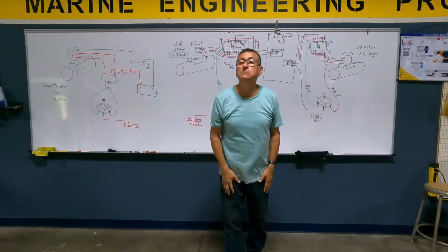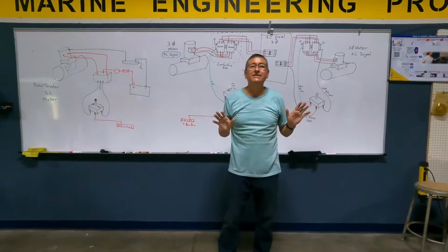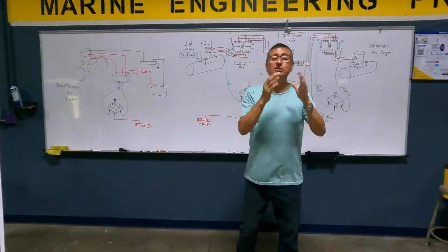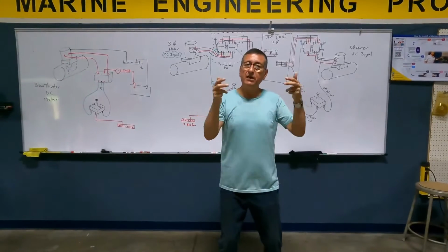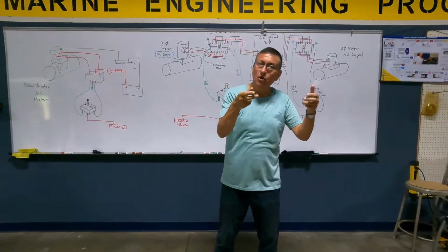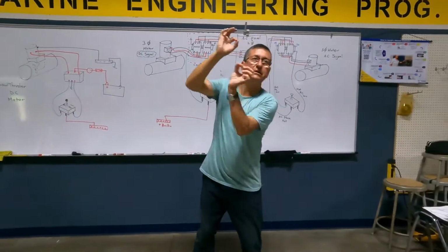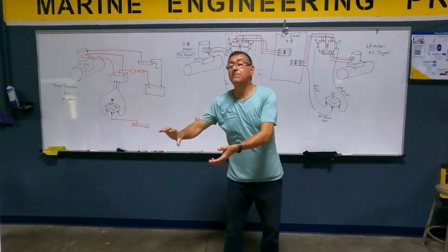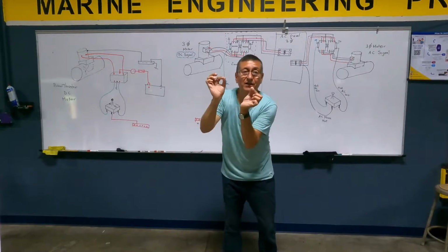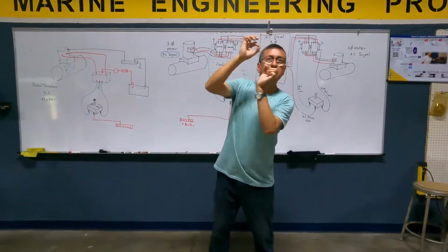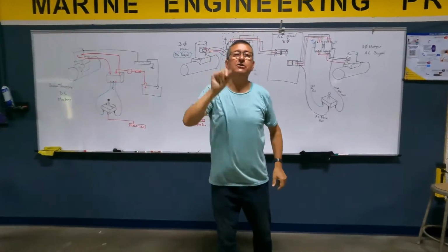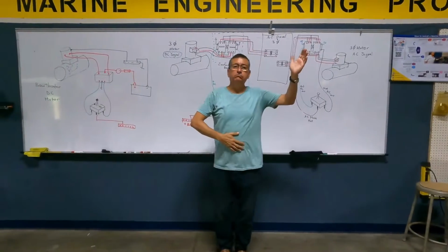I replace. You understand the process? I go to the control box. I identify if the signal for the contactor is AC or DC. If it is AC, let me provide AC externally. If it is DC, let me provide it with a battery and two alligator cables. Nothing. This contactor is damaged. Bingo, finito.